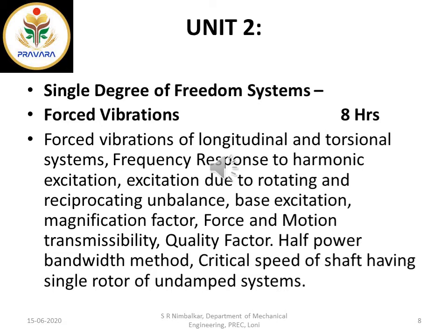Okay, or that is a forced vibration, because you are applying some motion, some RPM you are giving with the help of a motor, or some reciprocating action you are giving with the help of a reciprocating mechanism, isn't it? And that is one kind of external force application, and that becomes the forced vibration example.